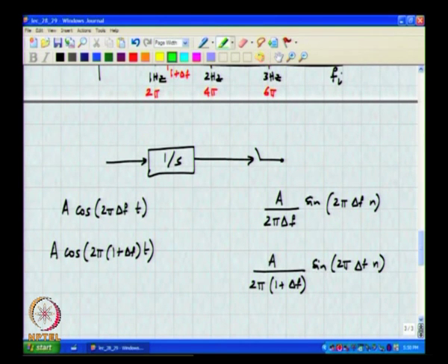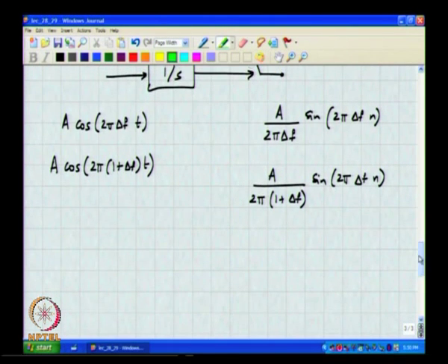This is well known, right, because sampling is involved, you will have multiple tones aliasing to the same discrete time sequence. However, you see that there is a big difference in the amplitudes, right. So, the discrete time system following this is the same in both cases, right. So, both these tones alias to the same frequency in the discrete time domain, after which the gain in the discrete time domain is the same for both.